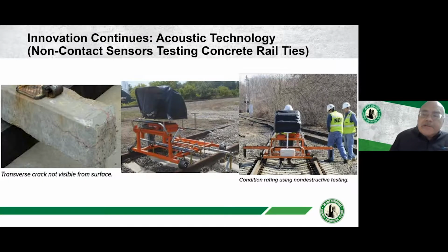Another area is the microphone technology. There are some very exciting advancements with acoustics, and NDT is proud to be a leader in that area. This was to determine cracks in concrete rail ties with microphone technology. We didn't have time to stop and have a contact sensor on the tie. We're just rolling by with a slightly different energy source, with microphone technology bracketing both sides of the rails.